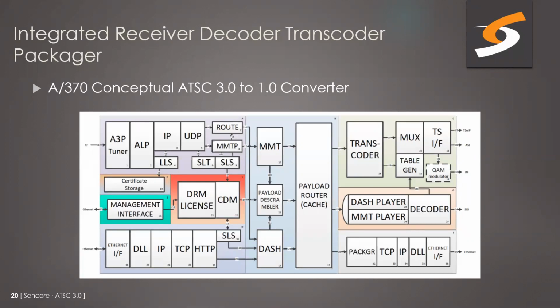I'm not sure anybody's going to come out with a single box that does all this in one for a reasonable cost or in a reasonable time frame, but it's certainly a goal: being able to take in ATSC 3.0 as RF or IP, and output that as IP, ASI, RF, SDI, and Ethernet with all the proper conversions in the middle. I thought it's a good try. I'm not sure how practical it is in the real world. We can talk about that more as we go here.